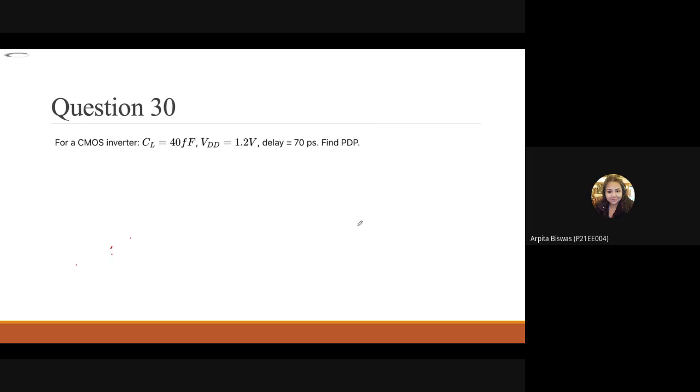For a CMOS inverter, CL is given, VDD is given, delay is given. Find out the PDP, power delay product.